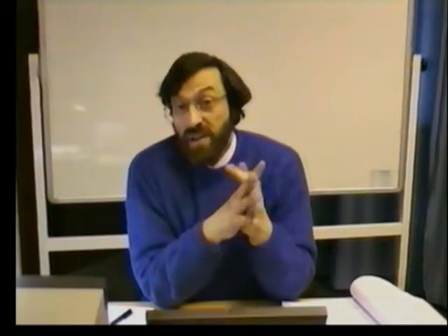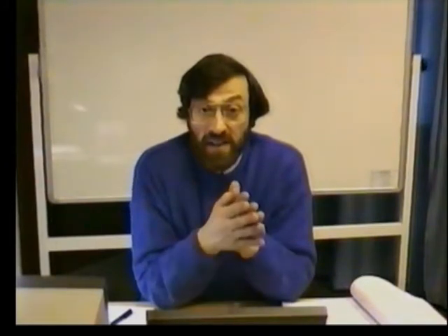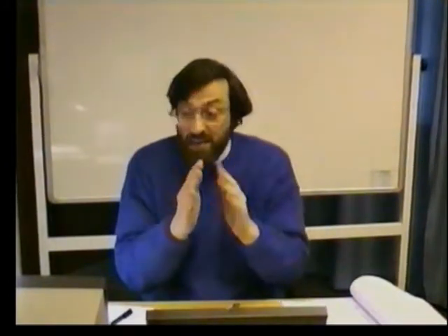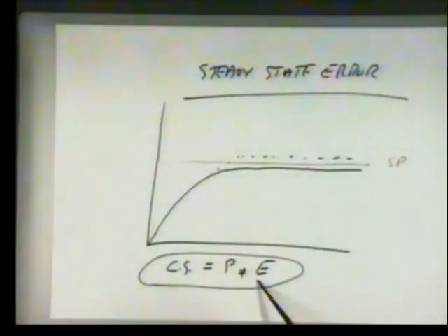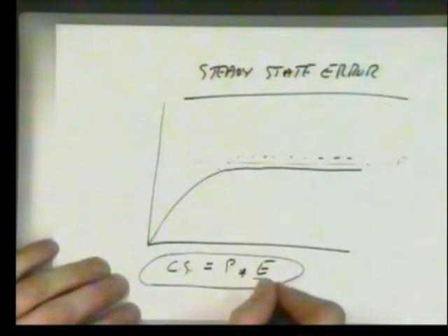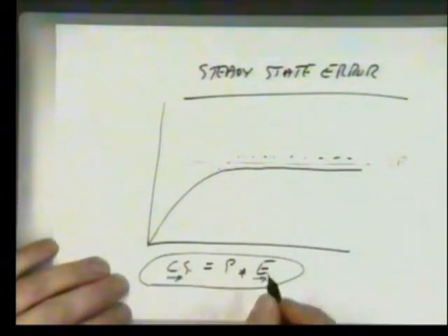How can we do that? Well, the reason our proportional controller has stopped operating is the error has tended to zero. If you think what's happening here, we've got a very small error. The error signal here, that's tending to zero. So the control signal that we're generating as a result of that error is also tending to zero.